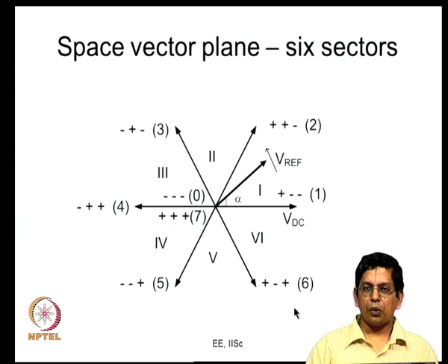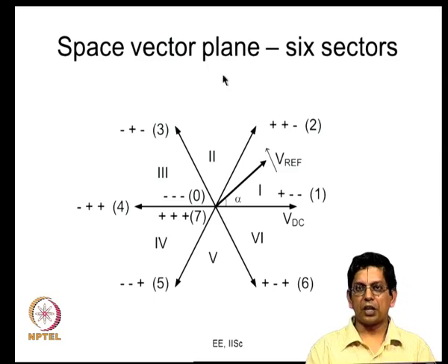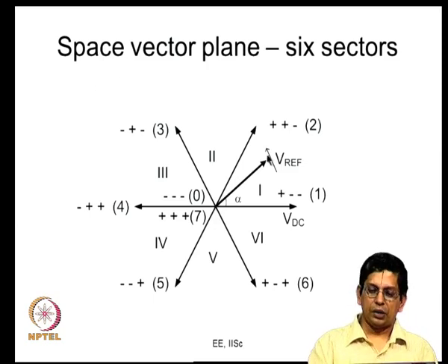Before we go into studying how the DC current is going to vary, it is better that we take a quick look at the space vector plane. There are 6 active voltage vectors and the 0 vector. There are 8 different inverter states. This is when all the bottom switches are on, this is when all the top are on. So, in these states you have a null vector getting applied. Now there are 6 other states, and these are called active states, as we have seen earlier.